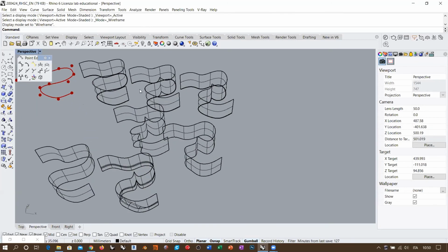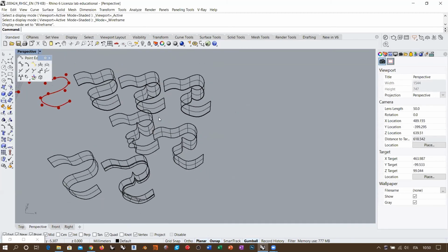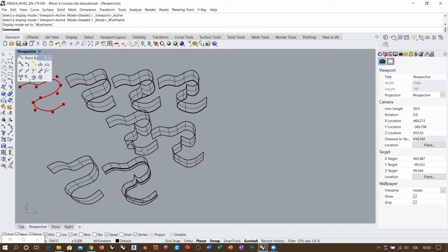For example, now we were working with extrusion, but I will not concentrate on extrusion because it's very easy to work with. It's important to understand how kinks and internal discontinuities work with a simple command like this. But once we know how it works, we can take advantage of this behavior in very complex surface modeling. Complex surface modeling doesn't mean that you necessarily have to use complex surface creation tools. So I normally recommend that between all the surface creation tools, you try to use the simplest ones.